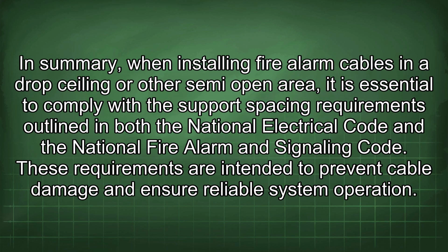In summary, when installing fire alarm cables in a drop ceiling or other semi-open area, it is essential to comply with the support spacing requirements outlined in both the National Electrical Code and the National Fire Alarm and Signaling Code. These requirements are intended to prevent cable damage and ensure reliable system operation.